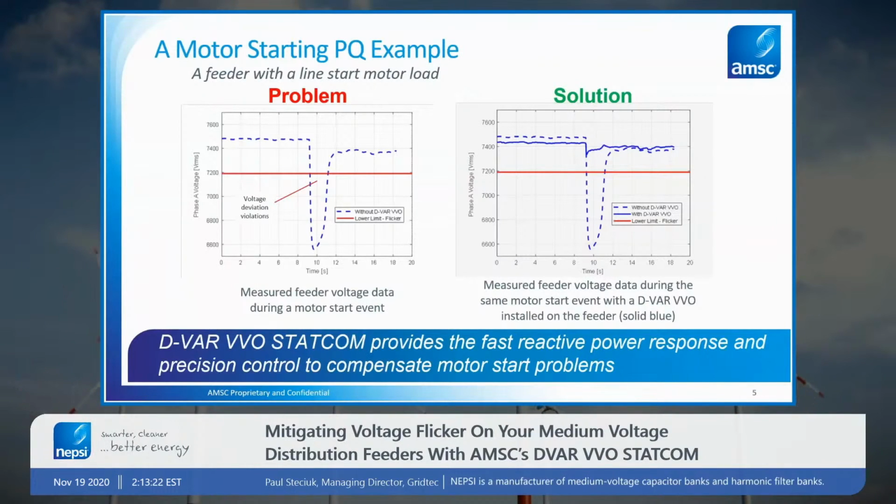That large inrush we talked about on the slide is what is causing this large dip in voltage across the inductive impedance of that feeder, and we can see it's well below the target threshold that the utility set for ensuring there weren't power quality issues.